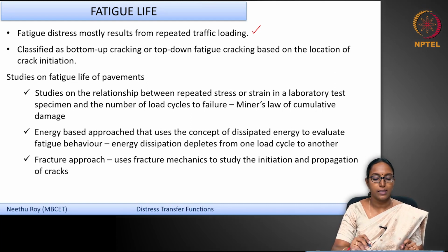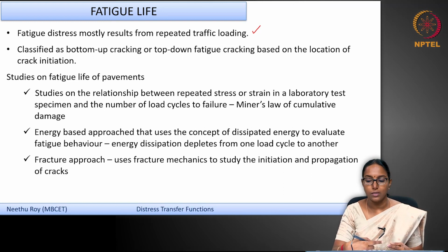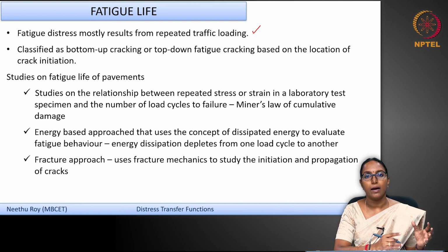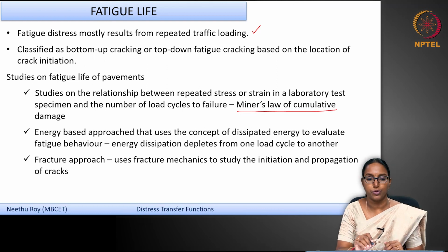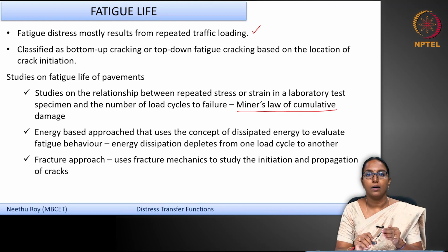The first one is that you will see what are the relationship between the repeated stresses and strains in a laboratory test on a bituminous material and its relation to the number of repetitions or number of load cycles to failure, okay. So, what you call it as a Miner's law of cumulative damage approach. You see how each load application damages this material and this can be accumulated to find out how this will perform in the field, okay.